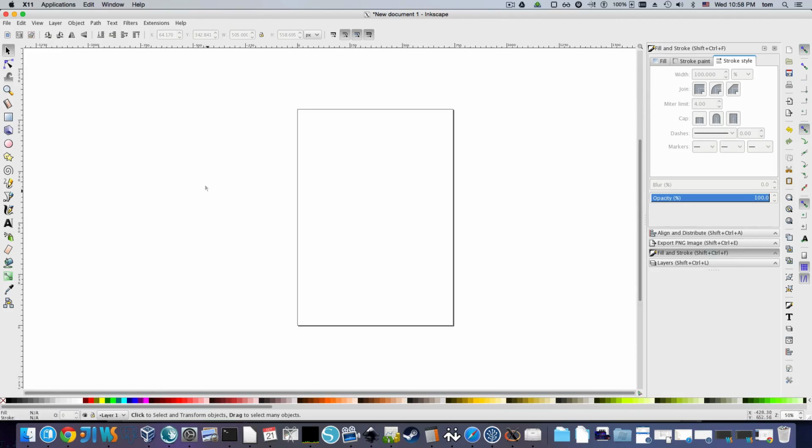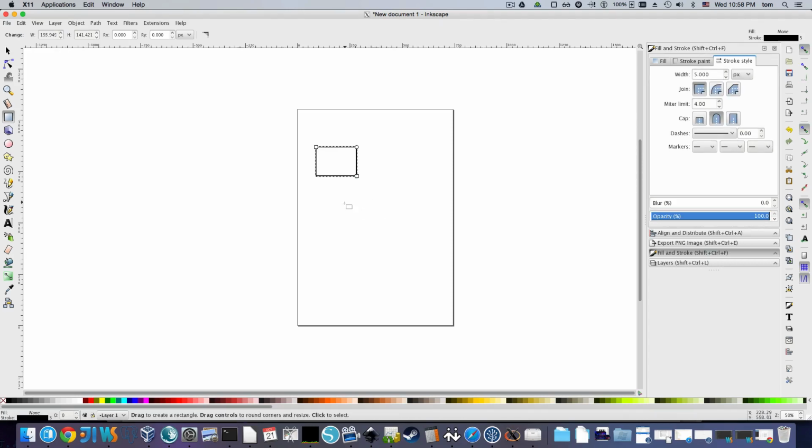So some basics with Inkscape. You can watch a ton of videos on this on YouTube, but I'll just go over the basics of what I use to get these drilling diagrams done. I've already shown you the box tool, which is helpful. You can draw boxes, and then you double click on them to go into edit mode, and up here you have your width and height, which is helpful. I like to work in millimeters because that's what most of the diagrams are in.